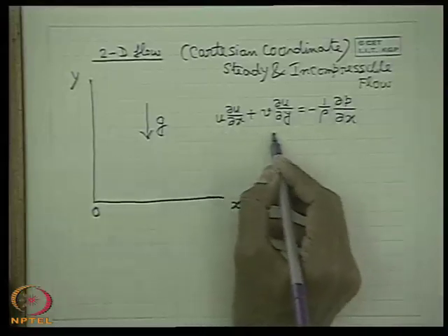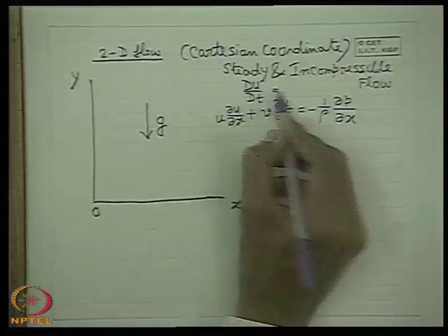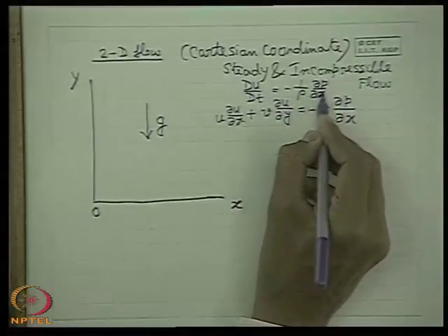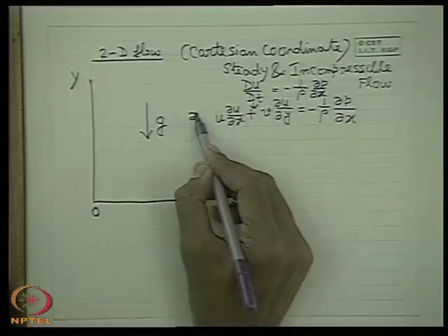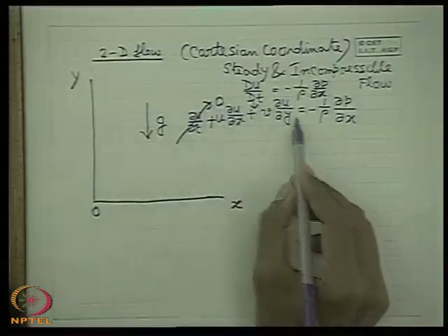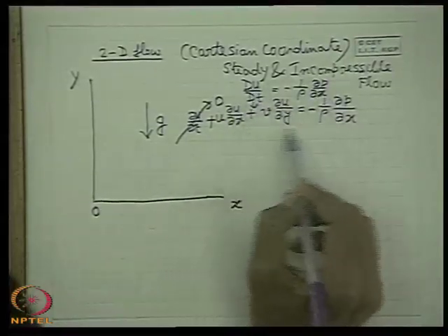So this is big Du Dt, and this is the x direction. So this has been expanded. Del u del t is 0 for steady state, so I have not written it. This is the x direction equation.